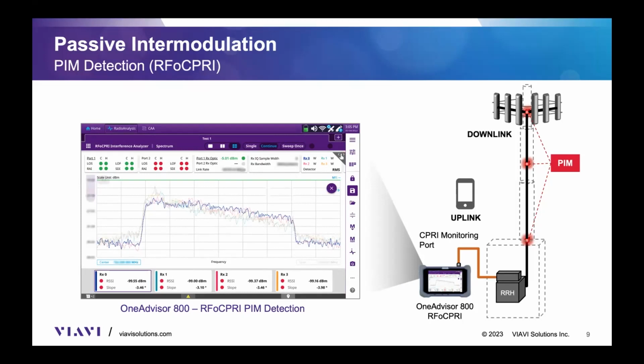So, for example, in LTE, we have heard about transmit, receive, multiple input, multiple output. That means that we have multiple antenna elements that are transmitting and receiving. Therefore, in this case, for example, we might have 4 different antennas, or MIMO 4, but that can be different configurations. One configuration might be that it's SISO, basically just one antenna transmitting and one antenna receiving, or MIMO with multiple antennas.